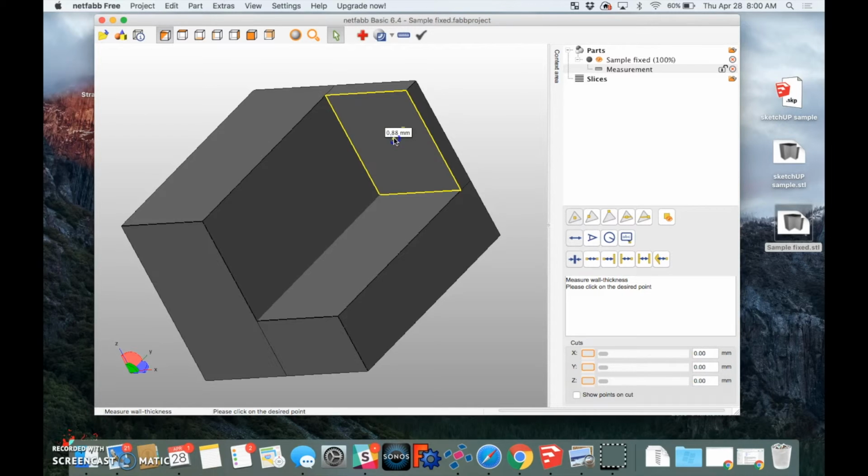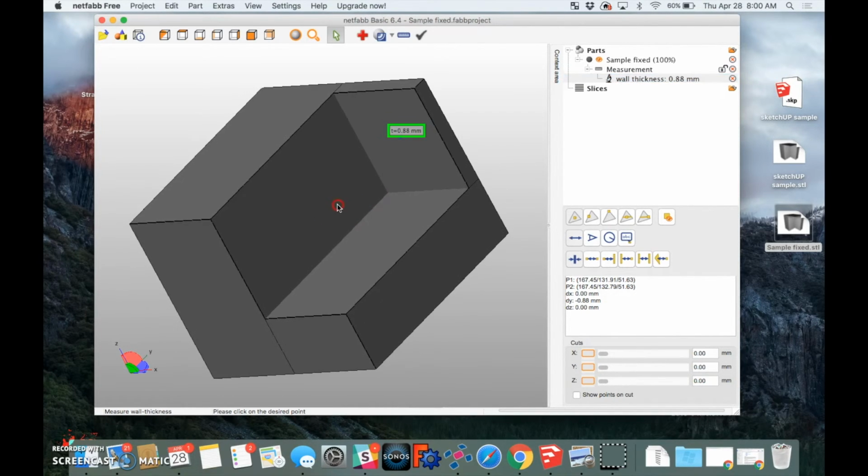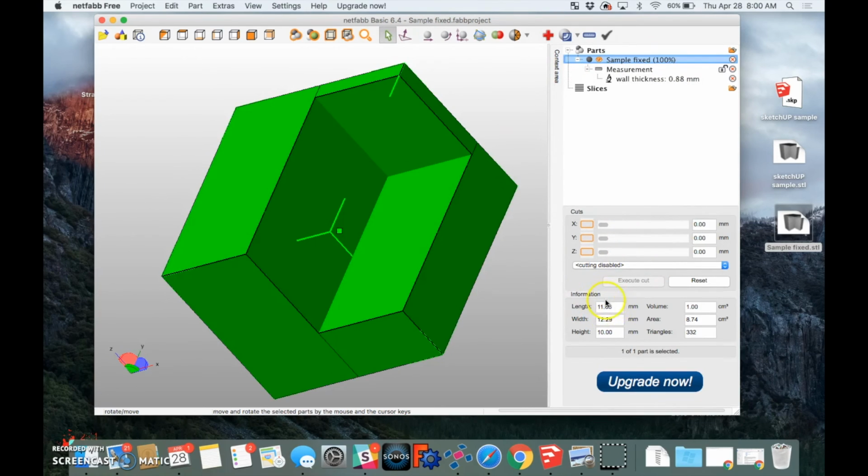It's our recommended minimum wall thickness, and that's important because if it's not 3D printable, sometimes if you're looking for the next stages, it's not going to be producible by other means like machining or injection molding, RTV molding. So it's something to keep in mind for scaling. Two things: when making it smaller, check wall thickness, and then when making it larger, check to make sure it fits within the bounding box of the build bed for the 3D printer.